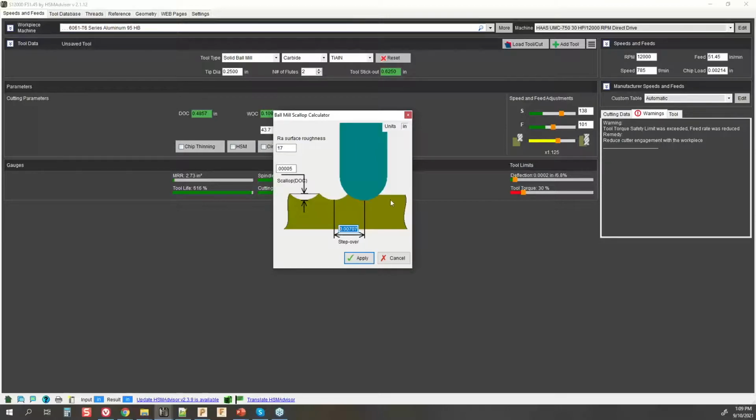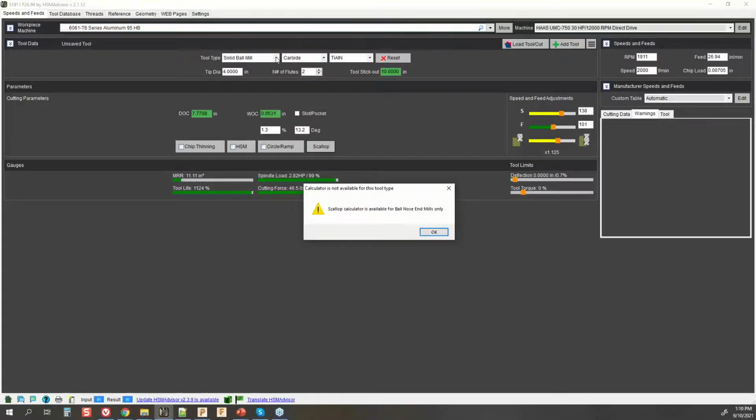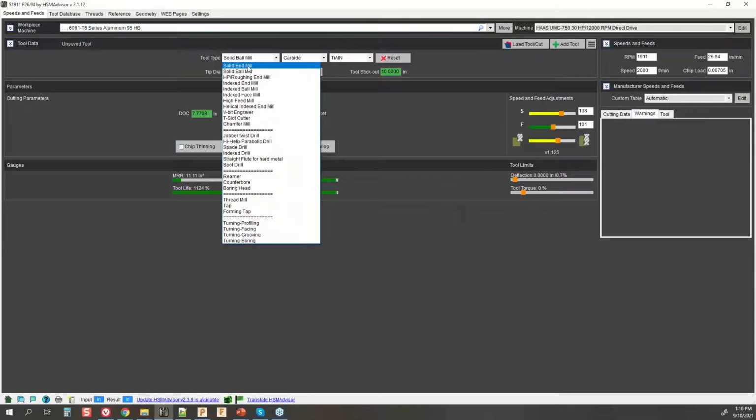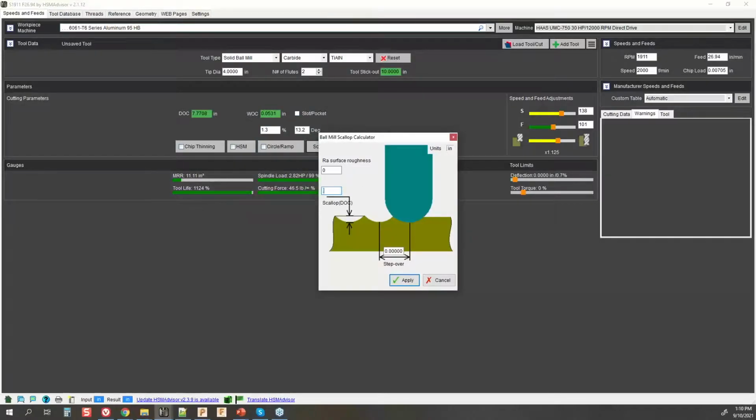But to give a good base example of what we're talking about improving here, these types of spherical tipped tools allow us to increase the contact point for that cutting radius 10, 20 times sometimes. So instead of a 250 thousandths tip radius, we can say maybe even a 4-inch radius for that type of cut. And when we do that and we look at our scallop height, and I do have to reset the calculator here to make that work, what we're looking at is a dramatic increase.